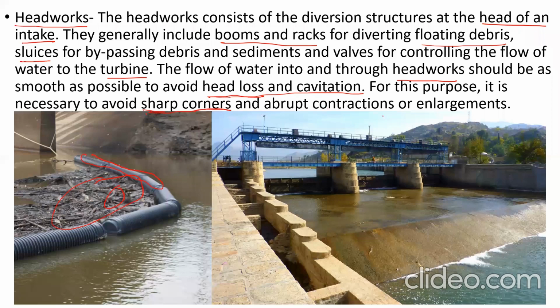Sharp corners and abrupt contractions or enlargements. You can see this is the extra canal along with the main dam. When debris comes, the debris will be removed from the water and the water is allowed to flow through this headwork structure, that is, canals. Headwork consists of booms and racks, means instruments to collect or remove those debris, and a canal with sluice gates.